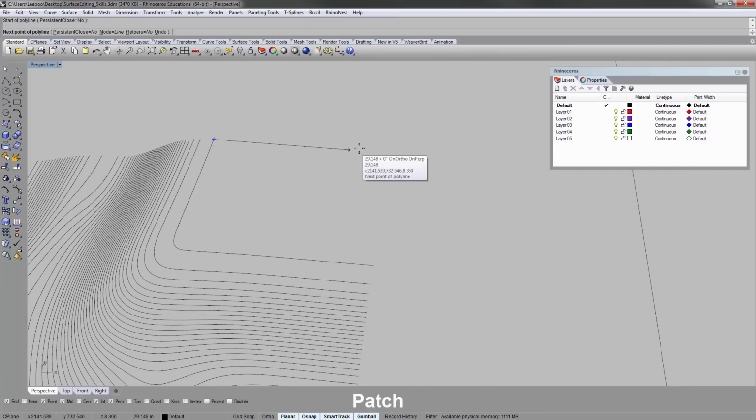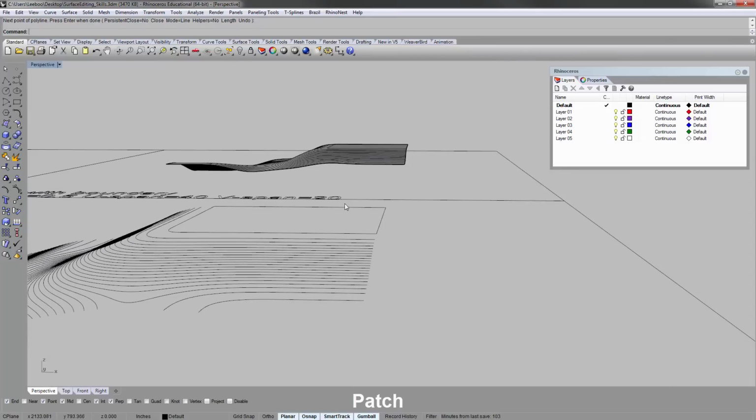So I'll draw a line, and I know this is on ortho going in one direction. I'll snap a corner, hovering over it, and drag it over that way towards the apparent intersection of these two. And you'll see this cursor pop up, perpendicular intersection. That's actually the intersection of this corner point, right?